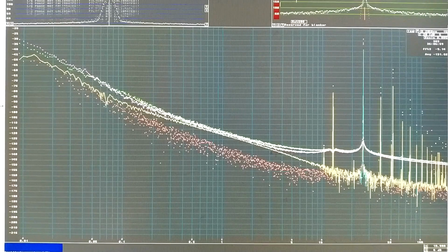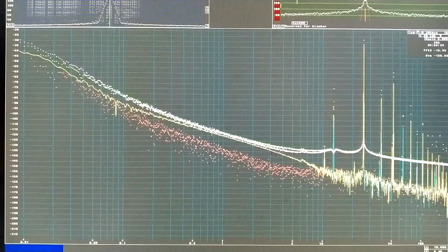I have added 10 decibels of attenuation between the Wenzel oscillator and my selective amplifier. And I have also increased the sensitivity of the 2-channel receiver. And here is the result. And what I had without that attenuator is like here. The difference is extremely small.